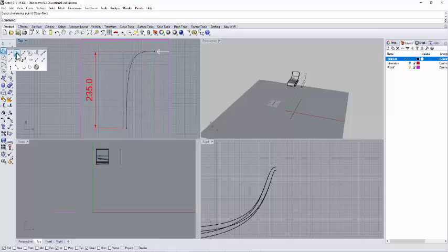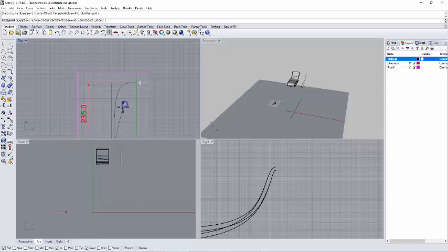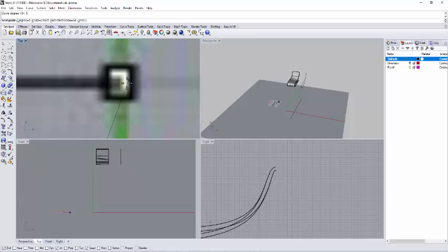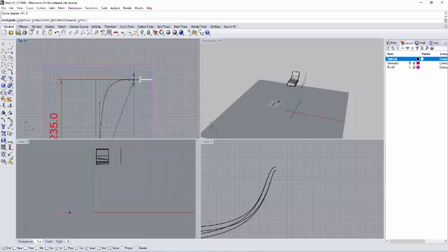So right now, let's say if I take an interpolate curve. Sorry, hold on, let me just hover on top. Interpolate points curve, right? Let me switch on my 235, which is here. Okay, how many points do I need? 1, 2, 3, 4, 5. If I need a 5 degree, let's say curve degree, let me put 5. At 2, 3, 5 here, right? Smart track on.